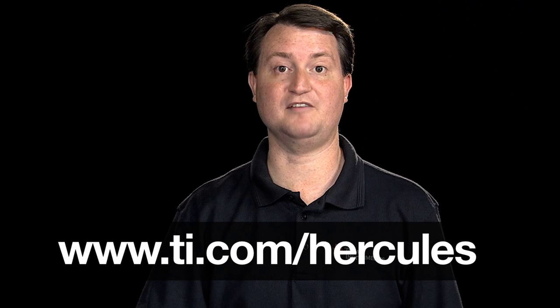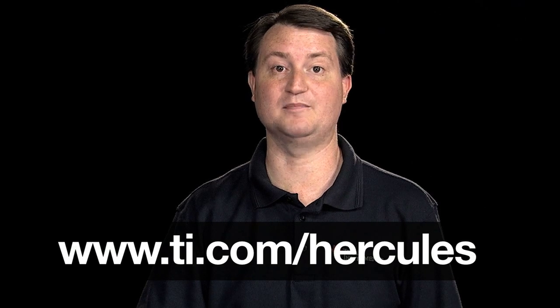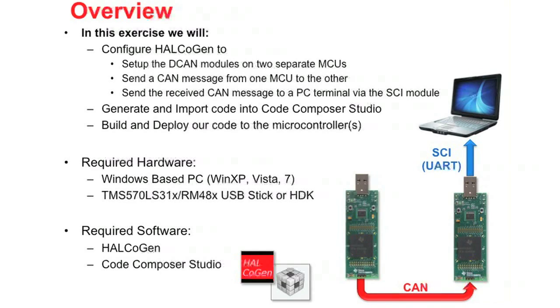If you do not already have HALCoGen, you can download it from the Tools and Software area on the website ti.com/Hercules. HALCoGen can also be installed directly from the software DVD included in all Hercules USB development sticks and Hercules development kits. In this exercise, we are going to set up the DCAN modules on 2 separate microcontrollers. Then we will send a CAN message from one MCU to the other one. Finally, we will send the data received in the CAN message to a PC terminal for viewing on the SCI module configured for UART communication.